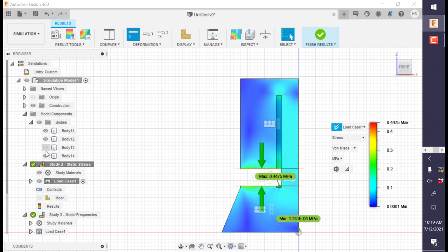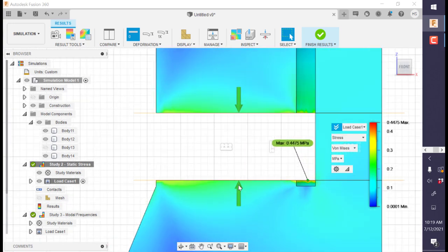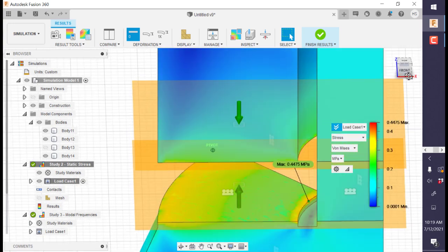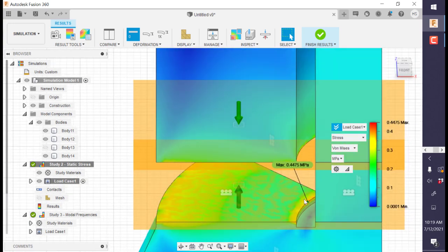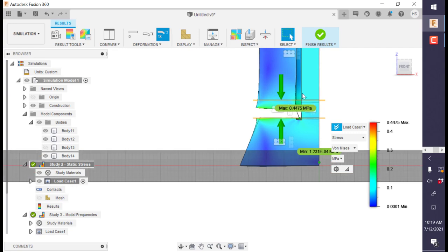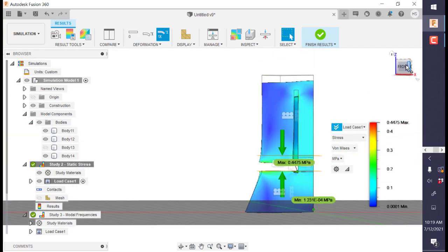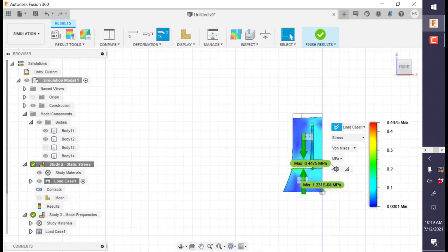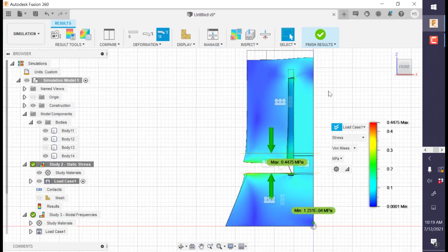we can hide the piezo. And by hiding the piezo, you'll see that the colors have now shifted. So you see where the stress is maximum, where you have large stress. These are areas, and we'll also deform it. We'll see where we'll have the most influence, because this is where the stress and the strain energy is being placed. Those are the locations and the places which will contribute to the capacitance.